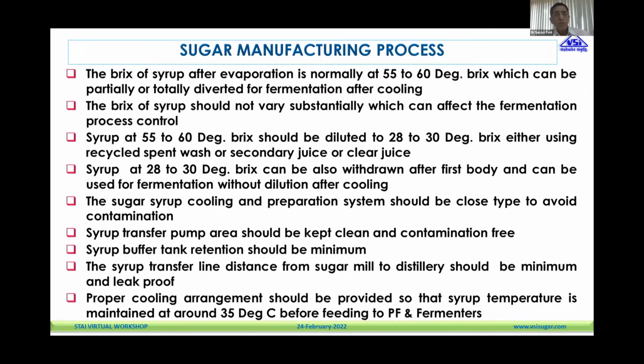The brix of the syrup is generally about 55 to 60, which can be partially or totally diverted for fermentation, depending on the capacity of the distillery, and of course after cooling. The brix of the syrup should not vary substantially, which can affect the fermentation process control.